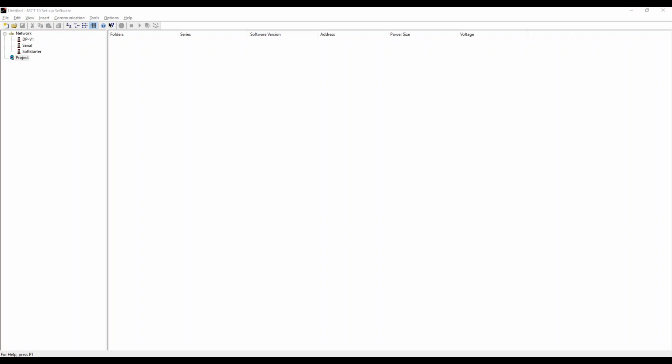If I swap that idea and I left on 2 and I toggled 3 for coasting and left on 4, 5, and 6, leaving start always on, and I just toggle 3. So when I turn 3 off, even though start's on, the drive will coast. And when I turn that bit back on, I'm no longer coasting. It will see start is on. It will start ramping. Right.